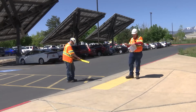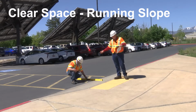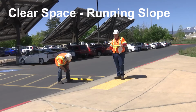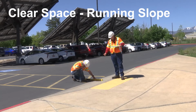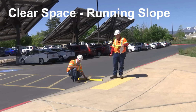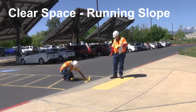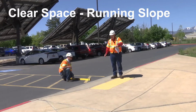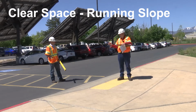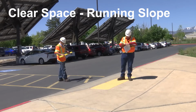So we'll take our running slope of the clear space. Here we have the gutter, and we also have the road. We have our split in between the two, so we'll want to take 2 measurements to see which one is higher and which one controls. First we'll take the measurement of the gutter, and it's 1.3%. And then for the road itself, 0.7%. So here we have 2 different values. We have the 1.3, and then we have a grade break, and 0.7. So which one do we put? We put the higher, so we'll put 1.3 as the running slope.